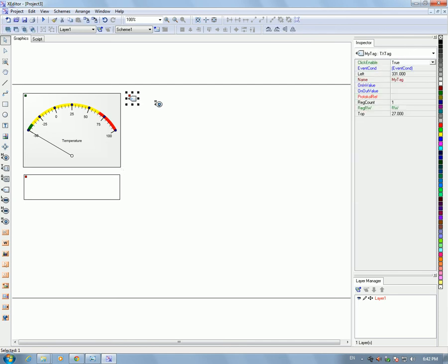Okay, I will connect this tag with the protocol, which is the TCP pipe port, this protocol here. Okay, my communication is almost done, and in this protocol I will set some data. It's the IP address. Actually, now I don't have different computers, and I will show how the TCP server program is connected with SCADA, which is localhost.